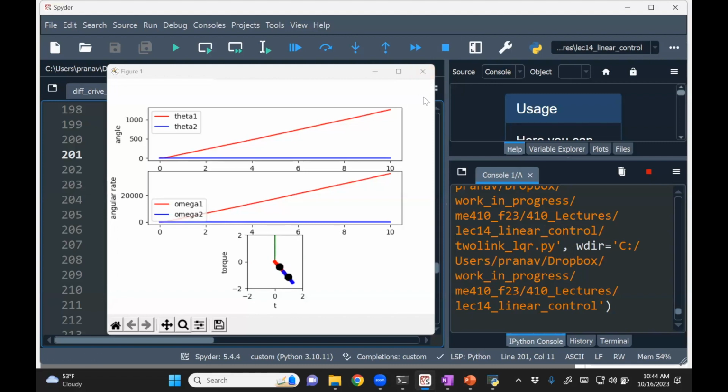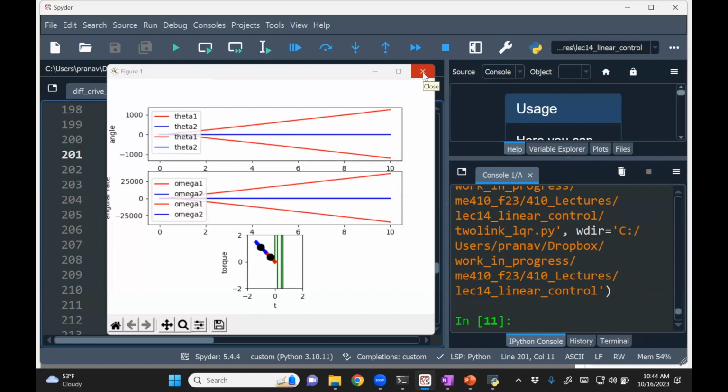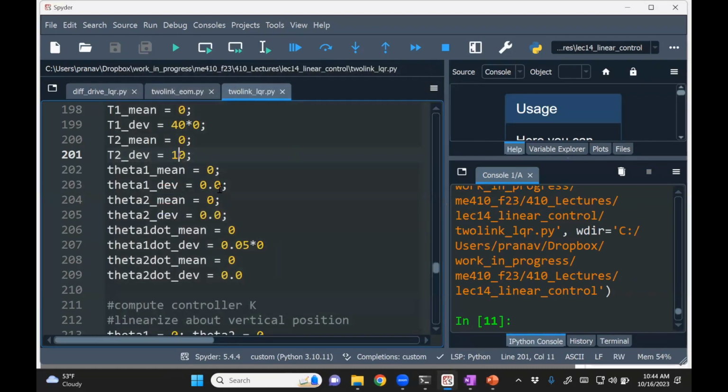Okay, so there is clearly a range where it can work, and it's not foolproof. Just because you find an LQR controller does not guarantee that the system will be stable, because remember that the LQR linearization holds about a particular equilibrium, the 0 point, and if you're too far away from that 0 point, it'll simply not work.